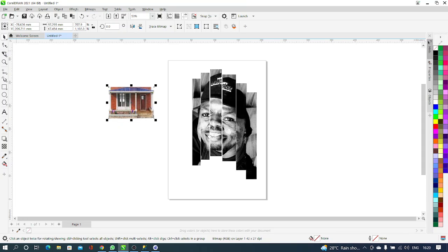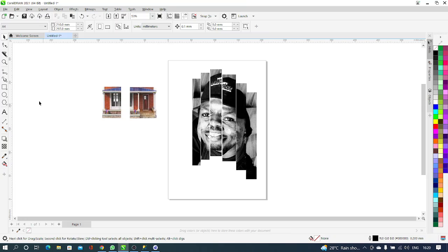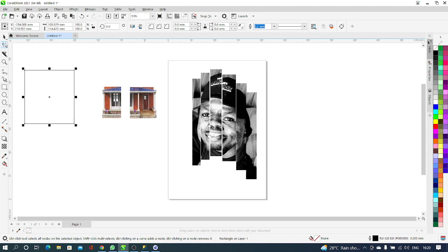I'll click the knife tool. When you see the edge written, you click, hold and drag down until it writes intersection. I'll release my mouse, click outside and click on the area you just cut. Now use the knife tool to divide. You can also apply it on an image just like this.